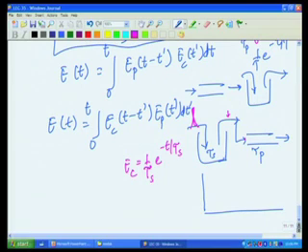At time t equal to 0, remember, suppose I were to draw a small sketch, at time t equal to 0, this is what is the input in the reactor, but we will not see that until time tau p has elapsed. Why? Because for a plug flow reactor, nothing that is coming into the reactor will be seen at the exit of the reactor till tau p time has elapsed, and there is no mixing.